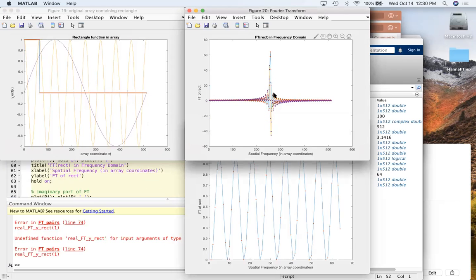What FFT shift does, it recognizes that the formula used for the digital Fourier transform gives you a peak at the k equals 0 point, which is the first matrix element of the array. And it says, no, that doesn't look too good. Let's put that point out here. And the higher frequencies go off in the wings, right? Now, this still just stops here. If we kept going, it would just have another replicant over here.